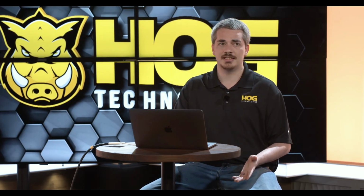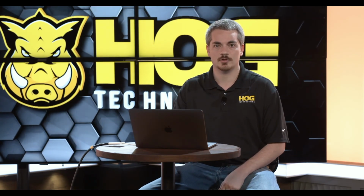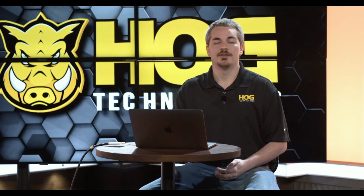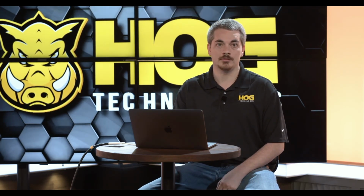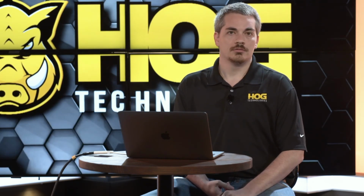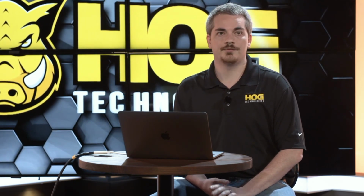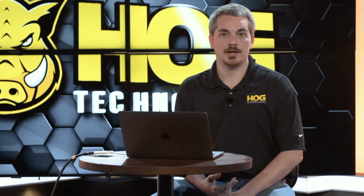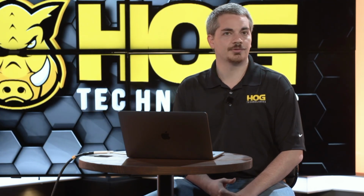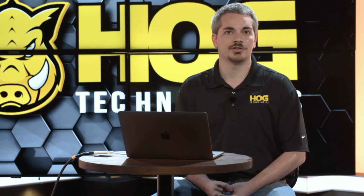So there are lots of different techniques to use with gas tungsten arc welding. Find what works best for you. There's no correct answer on this. The correct answer is the one that gets you the highest quality weld. So in recap, you were talking about your equipment settings, setting it up for direct current, pulse arc, AC, whatever you need for whatever you're using. Tungsten prep is very important. Clean your tungsten and make sure it's good. You don't want any contamination coming off your tungsten. And then just practice with different welding techniques. Find what works best for you and what works best for the joints that you're working on.